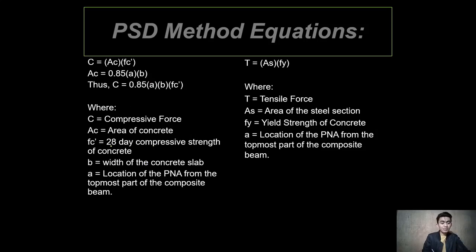Of course, Fc prime is your 28-day compressive strength of concrete. However, where did we derive this equation, 0.85 A times B for the area of your concrete? Take note, if you are going to recall your RC1, reinforced concrete 1, that is from your 2001 NSCP, or the National Structural Code of the Philippines,